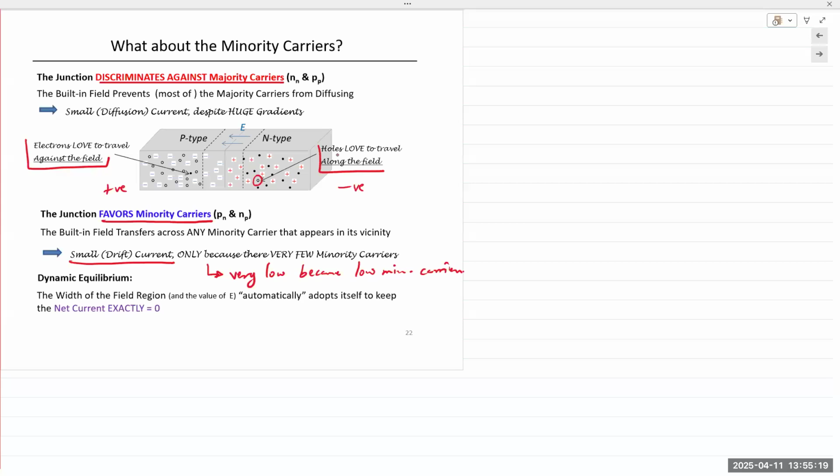Hold the questions I pointed out. And now, if we apply negative here and positive here, what happens? They're attracted, so they're going to pull away. If they're getting pulled away, that barrier is effectively being increased. So that's known as reverse bias. Let's take a pause, think over that. Let me know if you have questions.